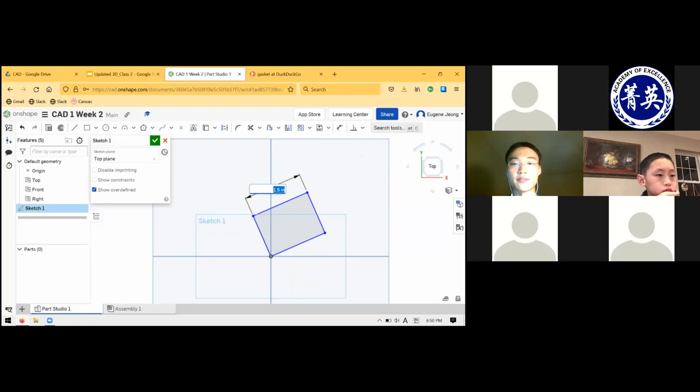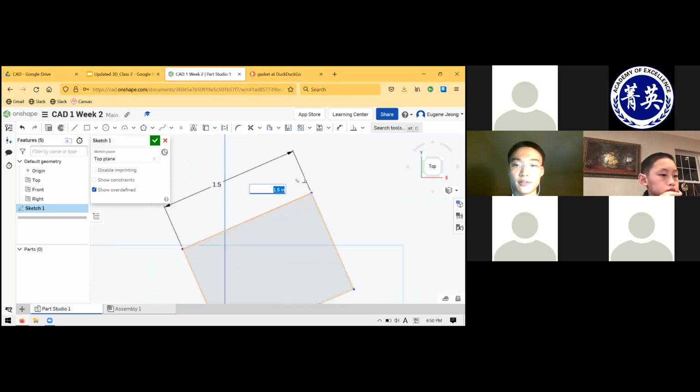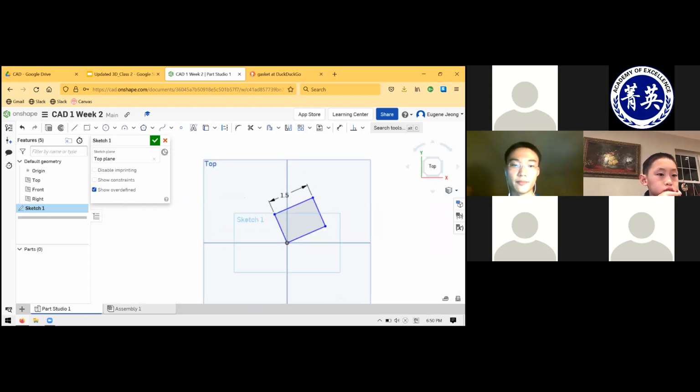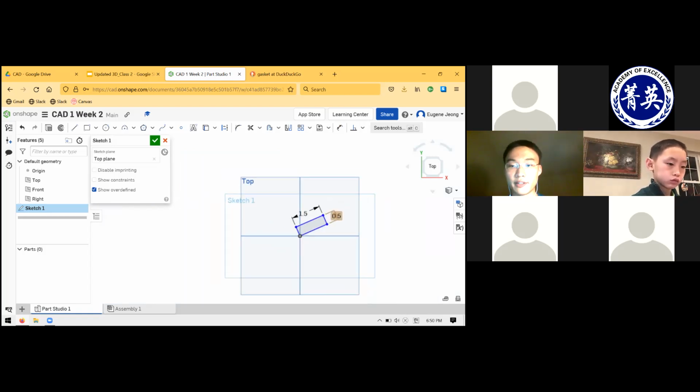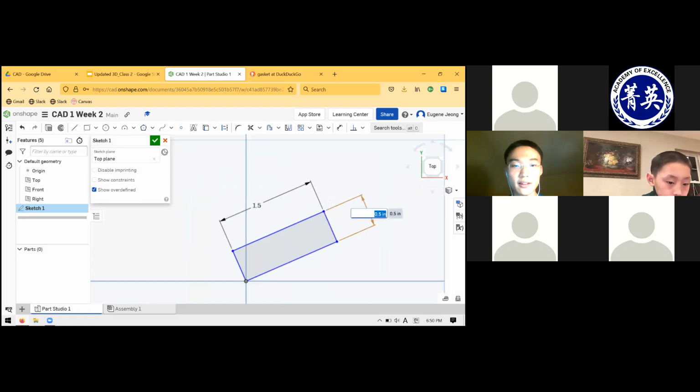As long as this text field is showing, it might limit what you're able to do, but I think you have to click it and then select it twice and then pull up the dimension tool. Okay, I'm not 100% sure, but if it causes a problem, let me know. If not, you do have to double click the dimensions to edit them. Clicking them once just selects it because you might be trying to do something that's not editing the value itself.